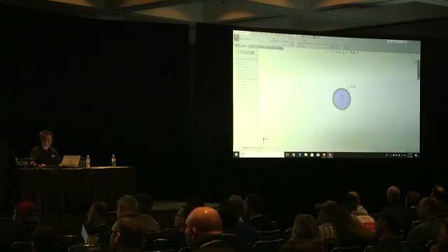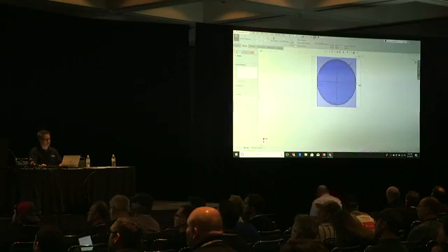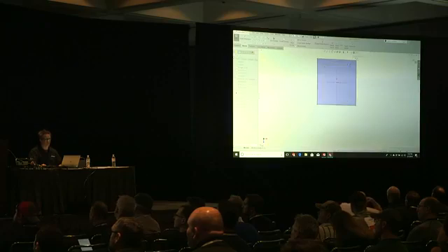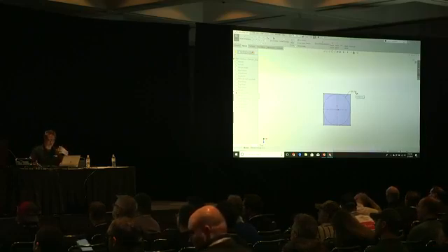Let's edit this sketch. And I'm just going to drop a rectangle in here. Drag it over, change this, and I'm using a lot of the pop-ups. Now the reason I left the circle there, I can still control it with that diameter, because that square is tied to the circle. Don't delete your geometry, keep it there.